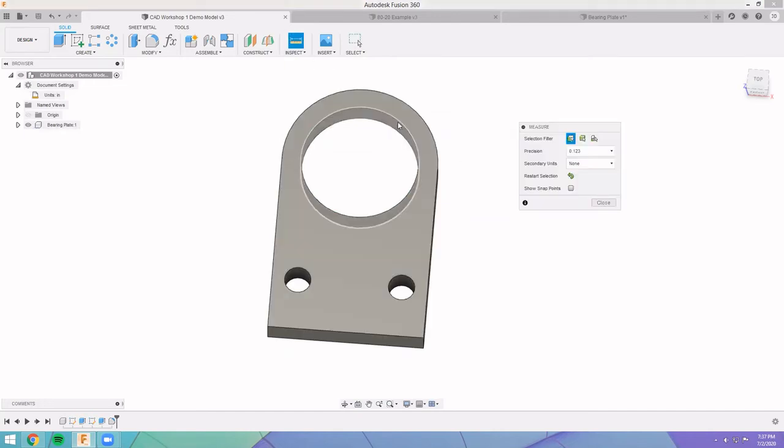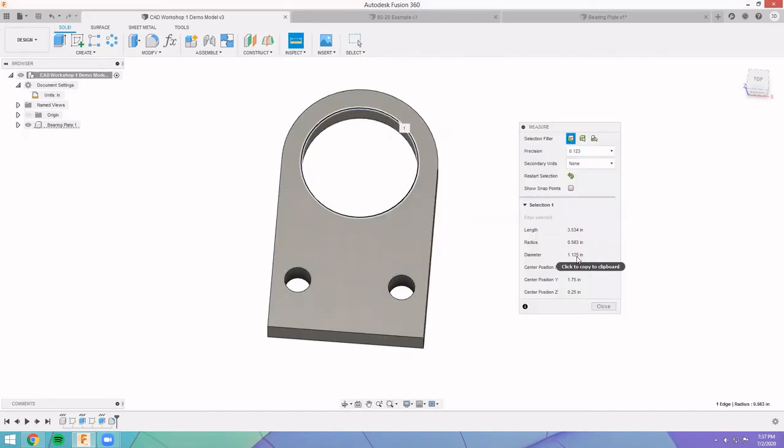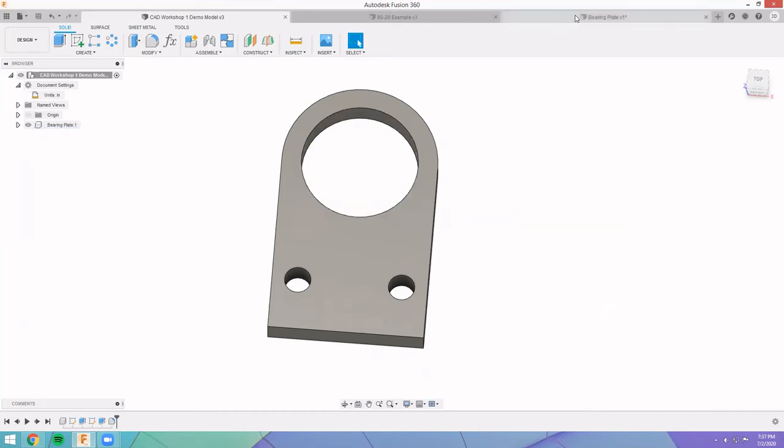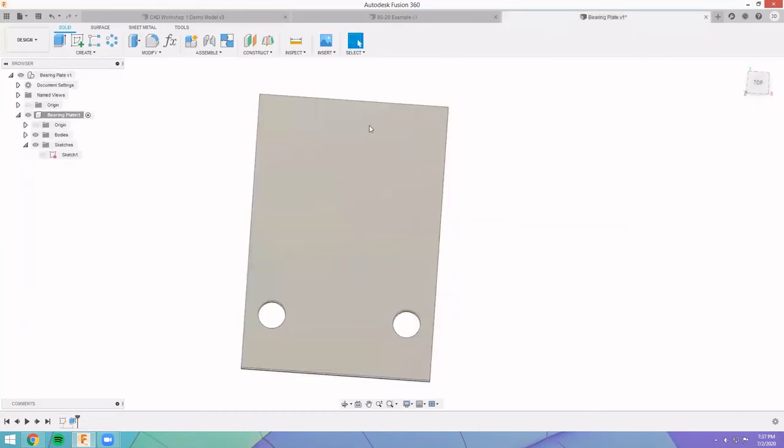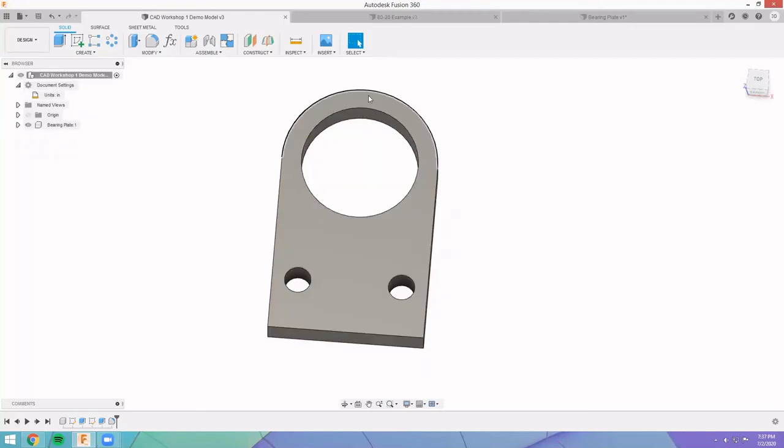This one, importantly, unlike the bolt holes, which we intentionally made a little bit bigger so that a bolt could fit neatly through it, this is a press fit, so we want to make this thing the exact same size or sometimes even a little bit smaller. So when we 3D print or cut this thing on the router, that hole comes out so that when we push the bearing in, it's a nice snug fit. So we need to make a 1.125 inch hole somewhere down from the top of this piece. And again, we probably want that thing right in the middle of this.